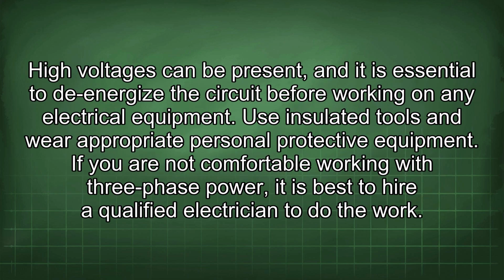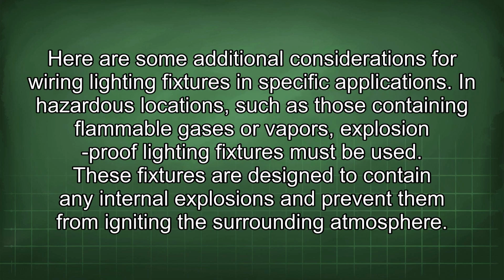High voltages can be present, and it is essential to de-energize the circuit before working on any electrical equipment. Use insulated tools and wear appropriate personal protective equipment. If you are not comfortable working with three-phase power, it is best to hire a qualified electrician to do the work. Here are some additional considerations for wiring lighting fixtures in specific applications.